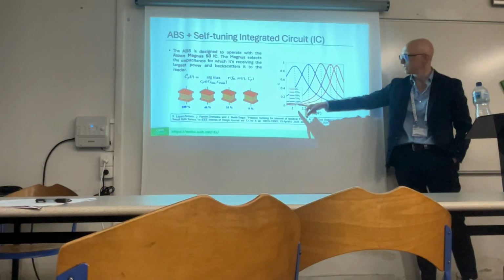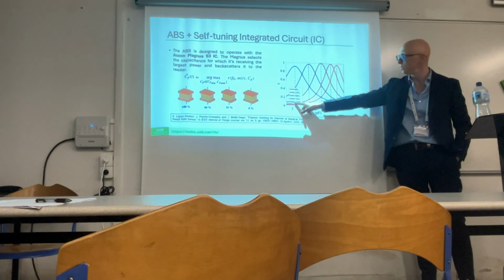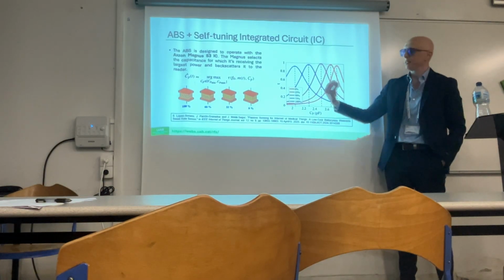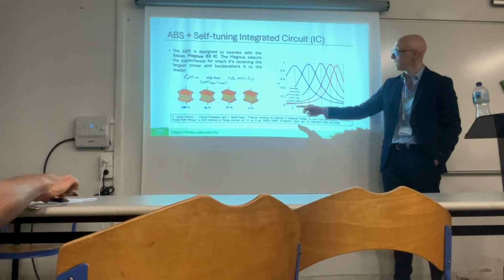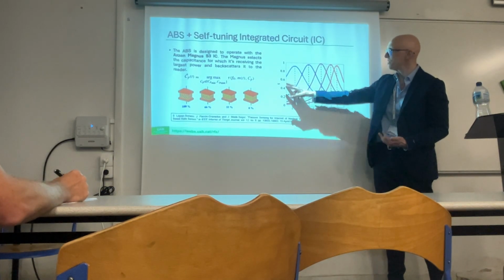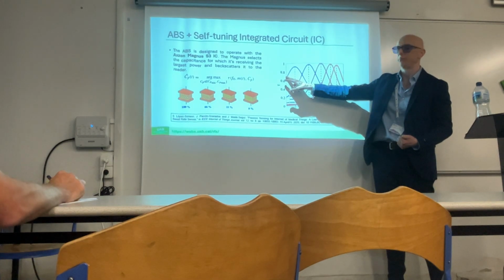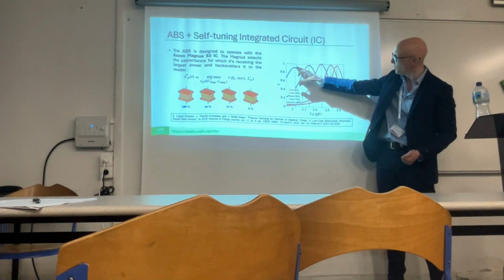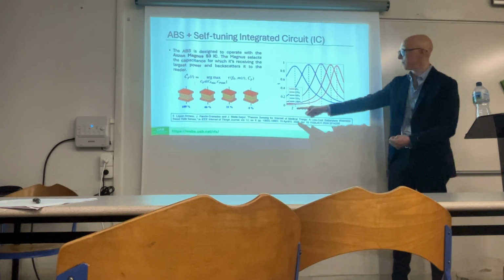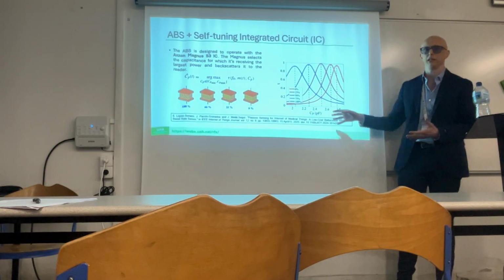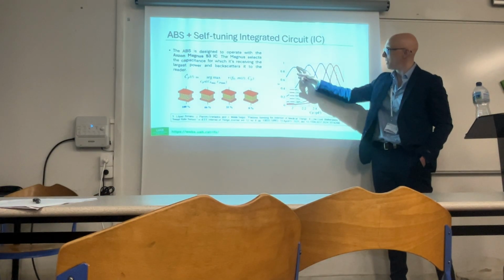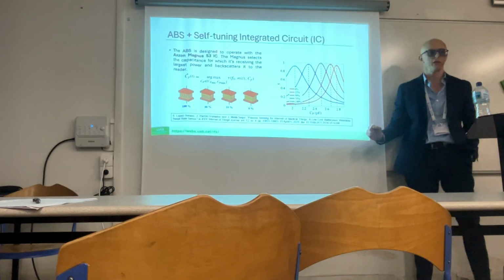As you see, for instance, in the case of the initial state where the absorbent is fully filled with water, we see that the microchip will sweep the internal capacitance value, and will measure the amount of power that is received by the chip. And then it will do it for each of the points that it can measure by changing the number of levels that the capacitor can program, right? And it will select the one that gives the maximum power, so the peak of these curves.